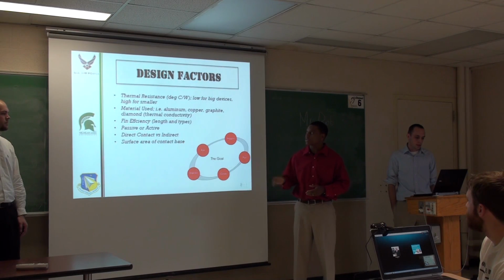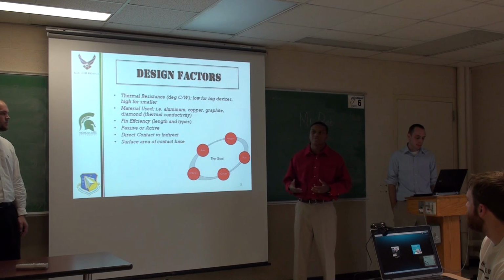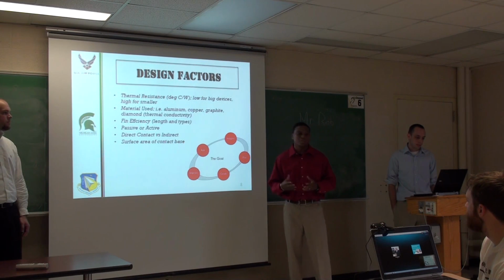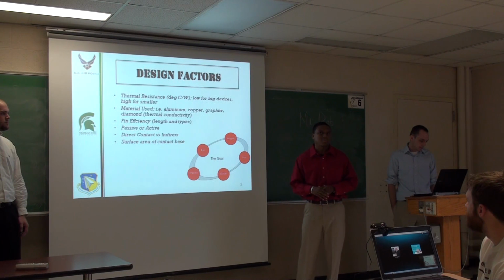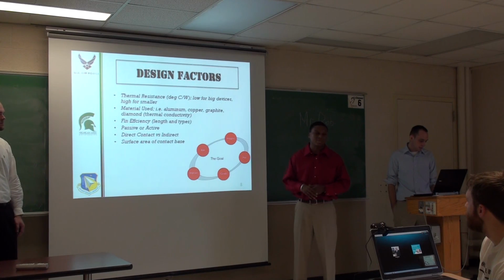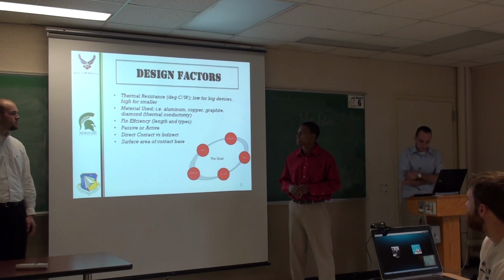You have the ones you've seen in figures 1 and 2. You also have circular fins. Those are more efficient in the sense of having a passive type of design. If you have about an airflow of 1 meter per second, the circular type fins are more efficient than all the other types of fins. Do you need a passive or active type design?